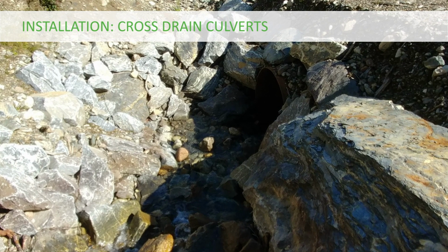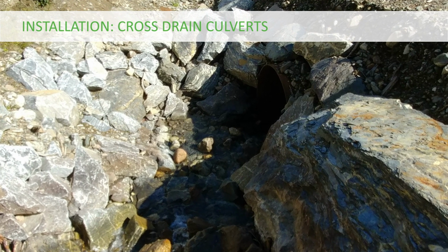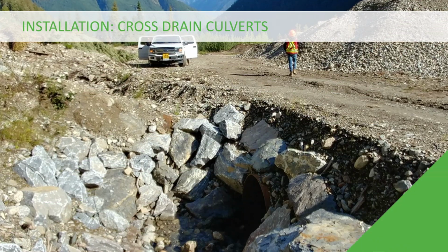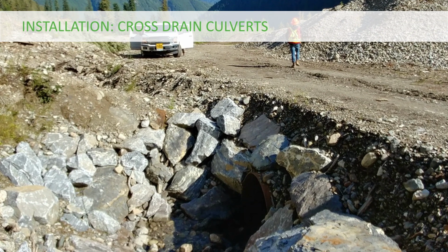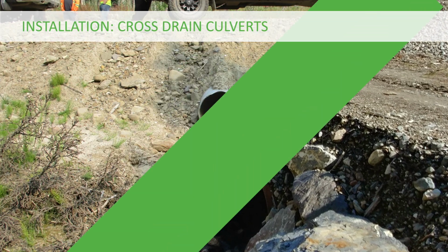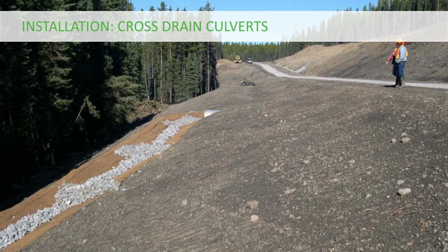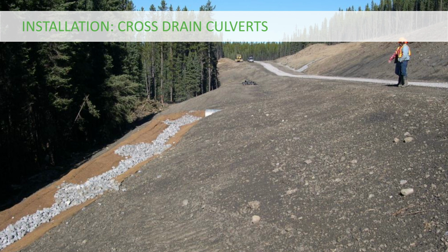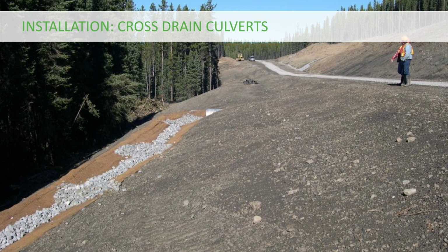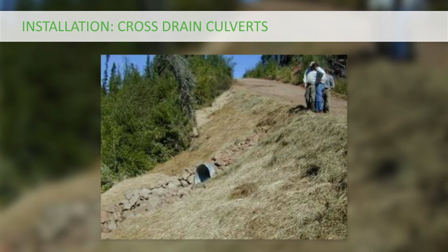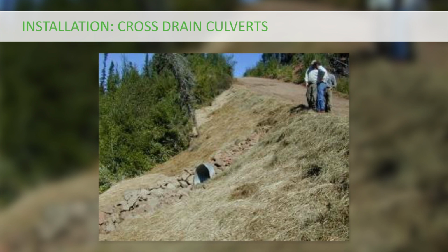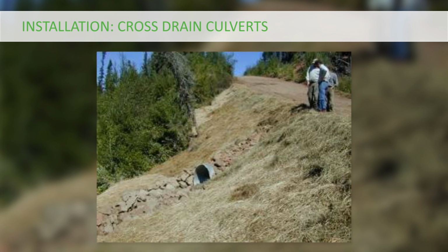Ditch blocks should be constructed to direct ditch flow into the culvert. The material making up the ditch block, likely soil and rock, should be well compacted. The outlet of a culvert should rest on natural ground surface. Where the outlet is within the fill slope, additional armoring will be required, and depending on downhill resources, redirection of the outlet flow may be needed.